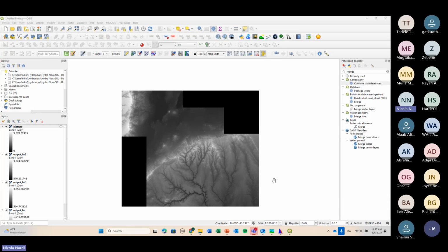Mainly, during the preliminary stage, what you're going to do is just, for example, the precipitation analysis and the basin abstraction. So, as your colleague was asking, sometimes with the satellite, or with other easy tools, you are able to extract more or less a basin. And in some cases, just knowing the dimension of the basin that you have to study is enough.